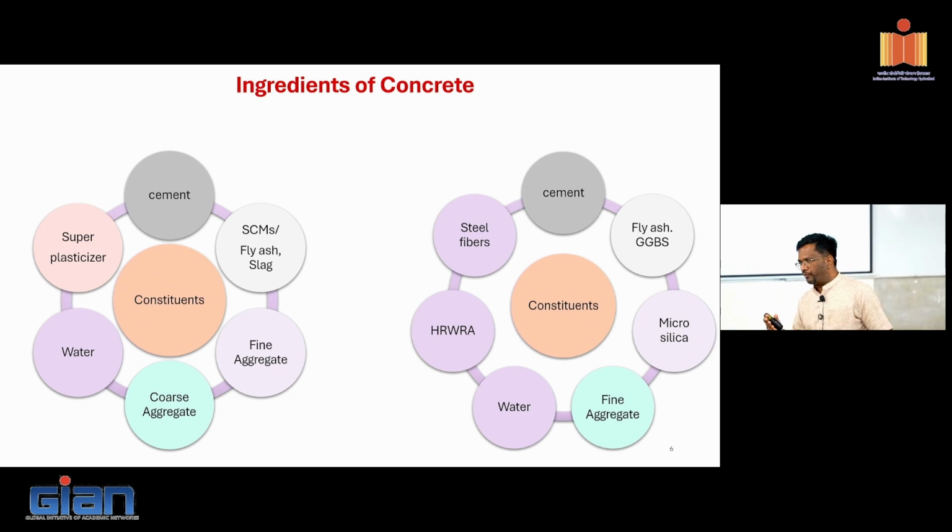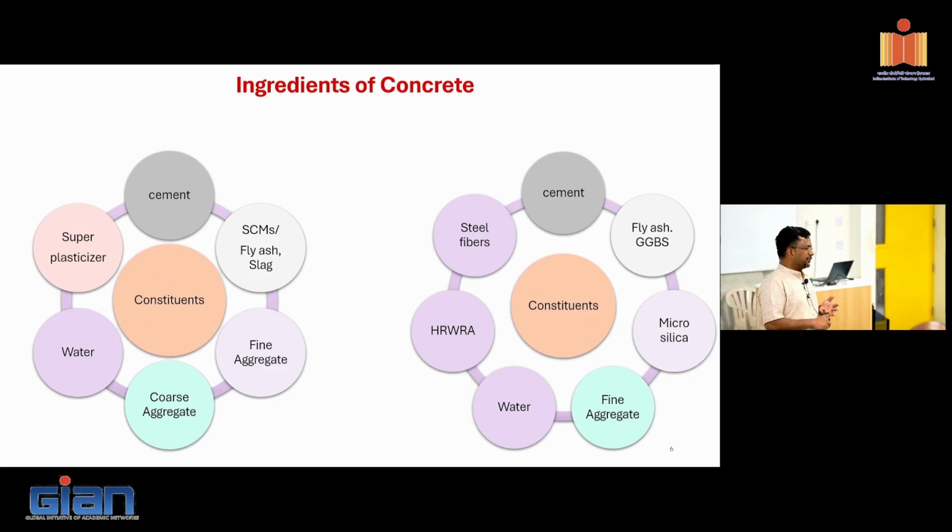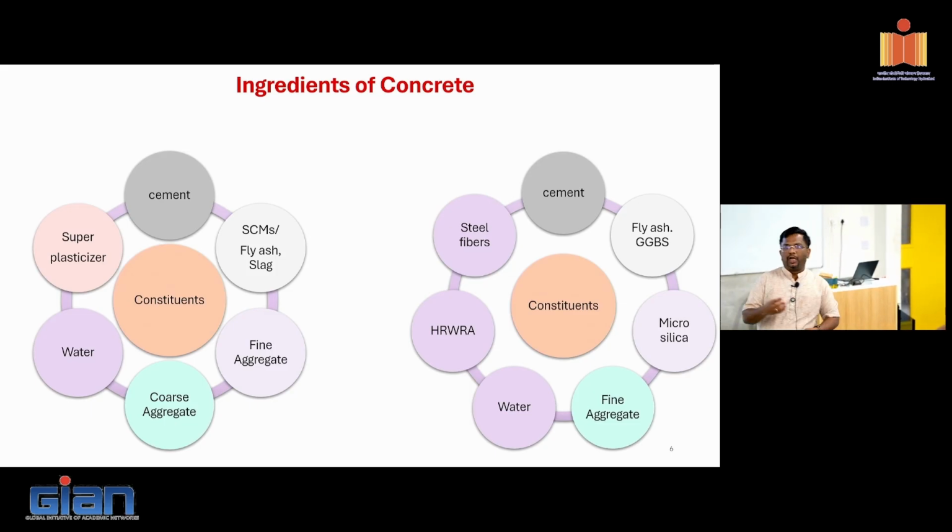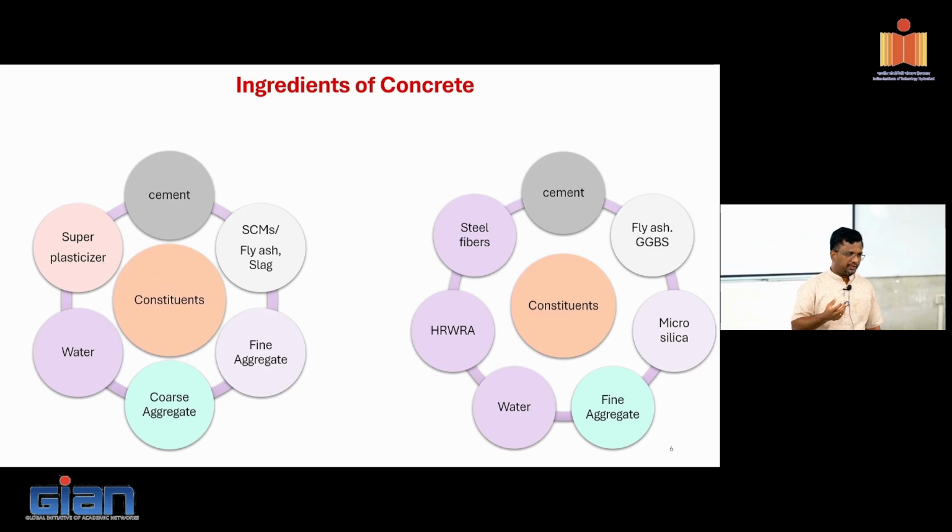So, if I am putting 0.4, what is going to happen? Workability will be high, correct. But what is the cost that I am paying for that? Strength will be lower, durability, what will happen? Yes, sir. It will be lesser. So, strength is going to be lower and my durability is also going to be lower, right? Because whatever unutilized water is in the cementitious system is actually the culprit that we are going to talk about, creep and shrinkage. That will try to come out of the system and that will create more problems.